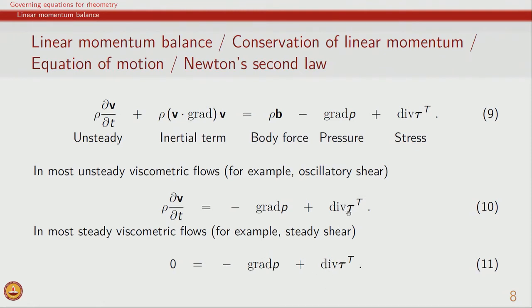We remind ourselves that we do not really know in some cases how the fluid stress depends on various kinematical quantities such as strain and strain rates. In fact, the purpose of doing rheological analysis and characterization using a rheometer is to observe how some of the properties change as a function of strain, strain rate and other kinematical variables.